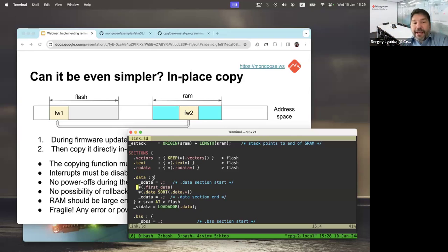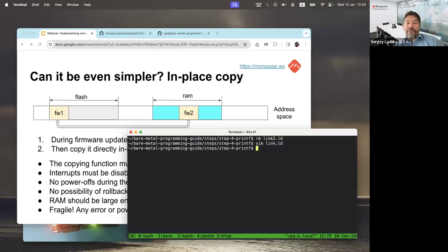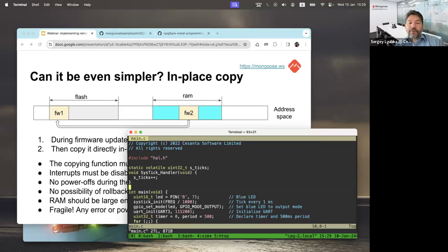But you can specify an ELF section manually. You can do it yourself, right? There is a mechanism for that. For example, if I open main.c and look at my main function, there is a GCC attribute, a kind of marker or trick, that tells the compiler to put that specific variable or function into a specific named section.